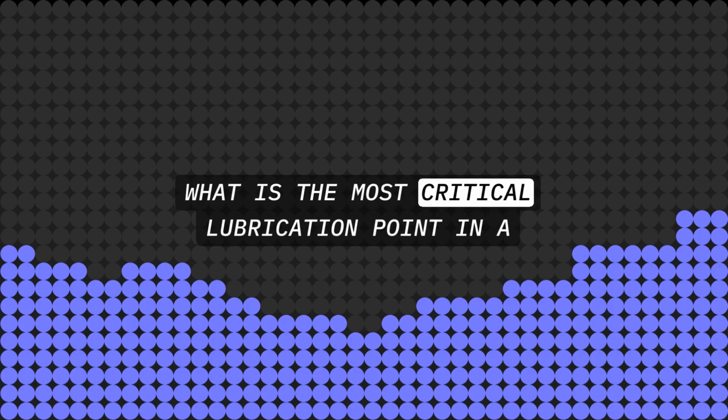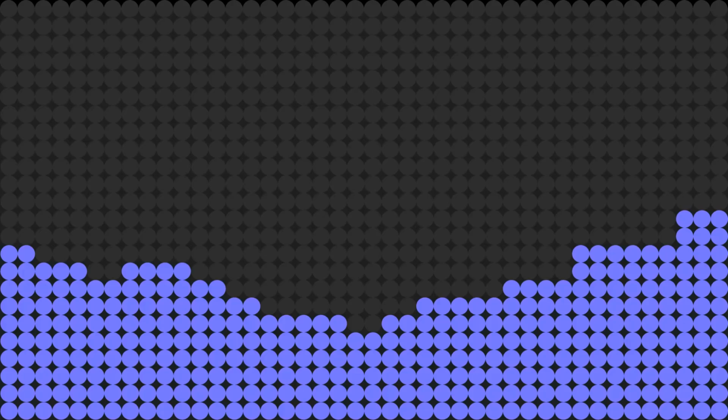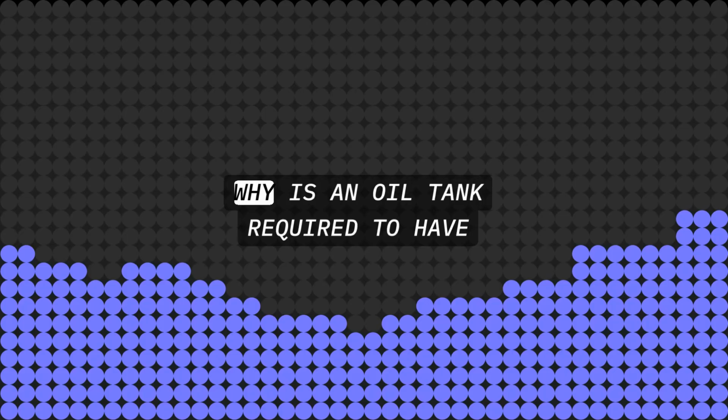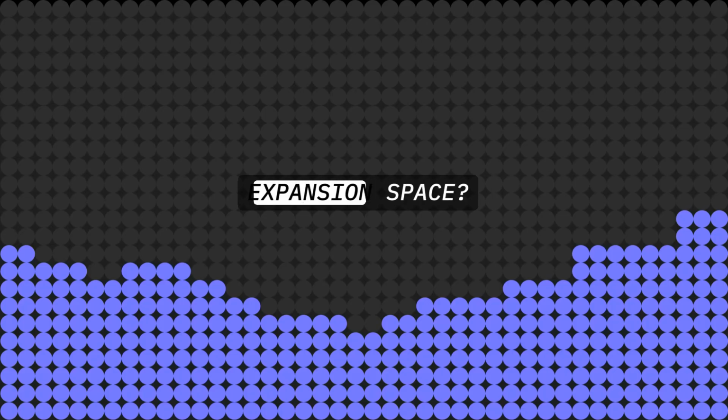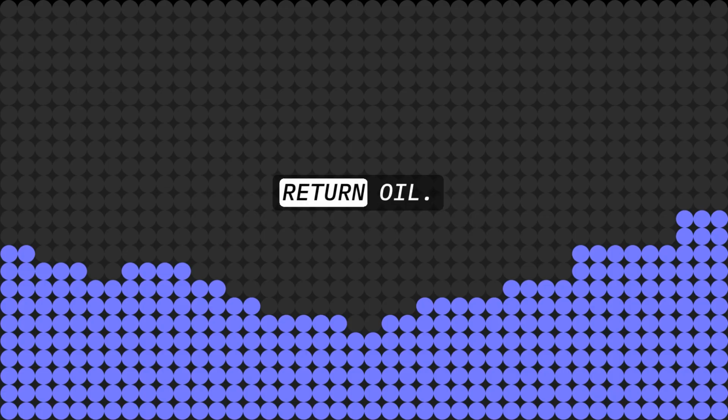What is the most critical lubrication point in a gas turbine engine? The turbine bearing. Why is an oil tank required to have expansion space? To provide for thermal expansion and air in the return oil.